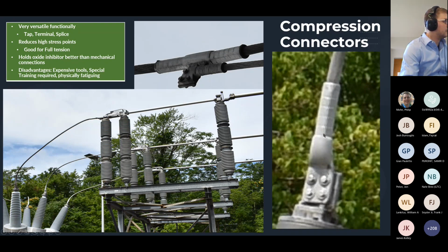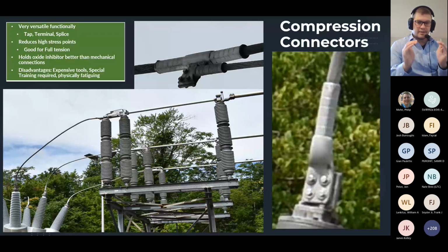And if we're looking at this picture here, you can see tiny little lines. This is showing you they actually crimped this 1, 2, 3, 4, 5 times. You work your way from the four-hole pad to the end of the barrel when you're crimping. And if you can see me on the camera, the difference between using a compression versus a swage: if you were to take your hands and make two circles and push inward, where your left hand is pushing to the right and your right hand is pushing to the left, you essentially only have two forces pushing inward. And that is what a compression connector is doing. It's basically smushing it top, bottom, left, and right, smushing the barrel to the connector.